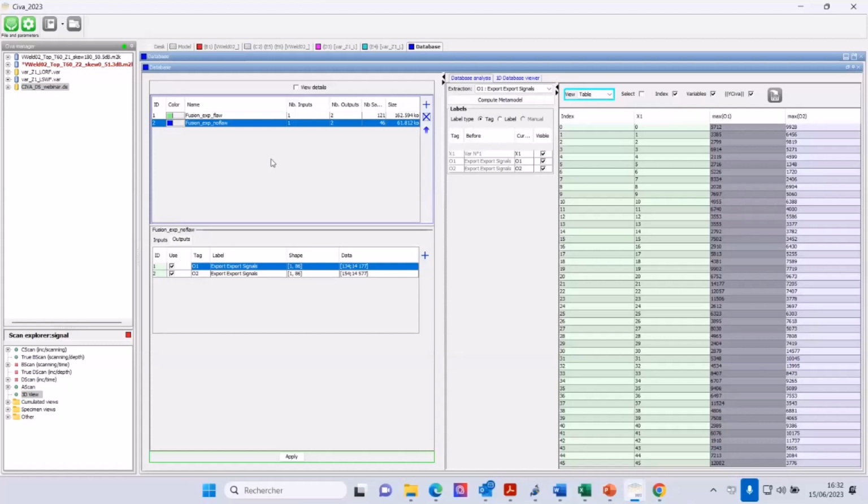We performed that on a backwall echo. We took 0 dB and compared the values in CIVA points and the values in the experimental data. And we found, in this example, the normalization factor. So we need to apply this normalization.